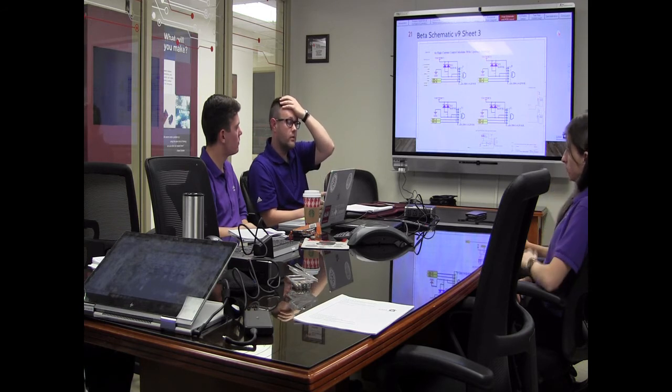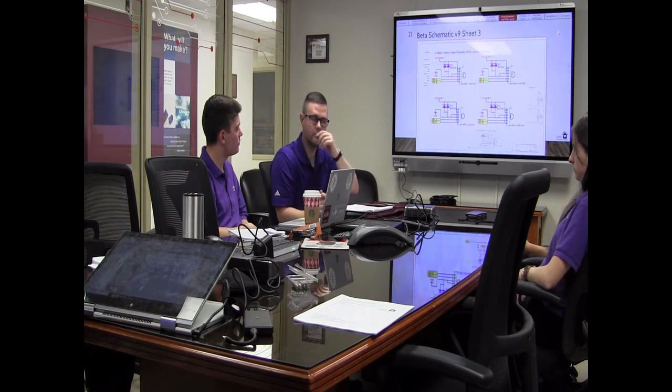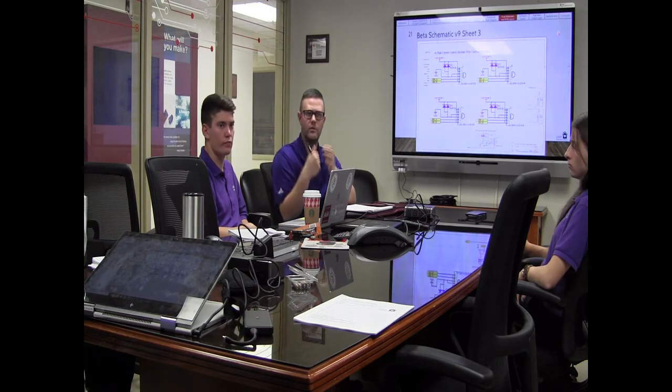And what was the connector to the load wiring? That's a good point, because it would have been our standard RJ12 jack, and then we're using Cat5 cable, and then, because it was only in testing, we were just using those little GPIO short wires with a male and female on either end. You mean jump wires? Jumper wires, yeah.